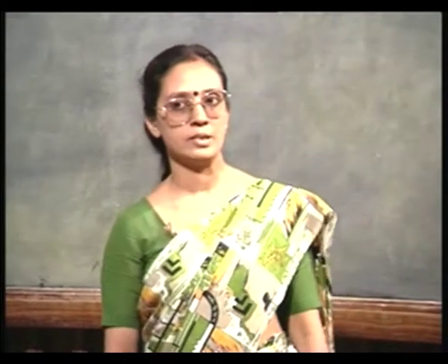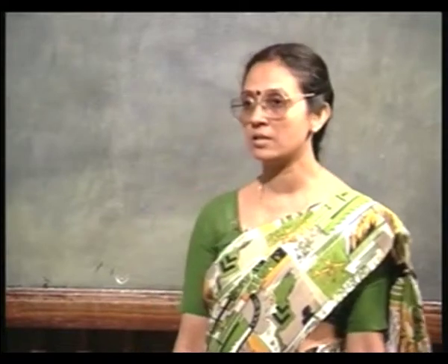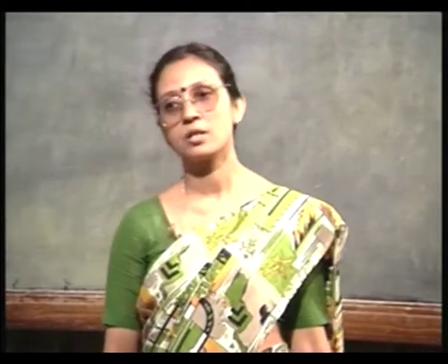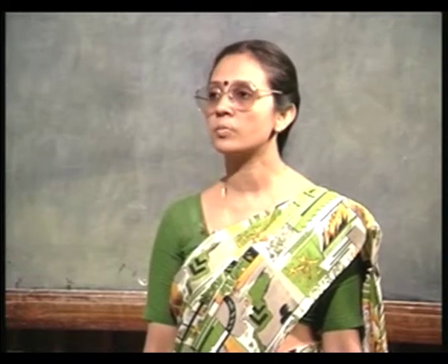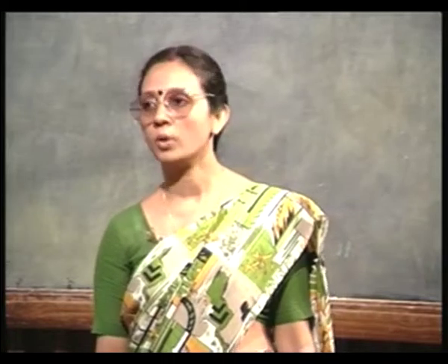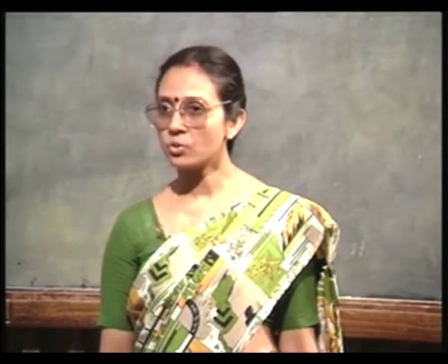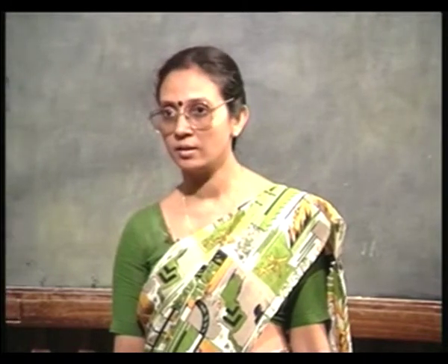What is the advantage? The advantage is that here I do not need, repeat, I do not need a crucible. In the Czochralski system, we needed a crucible to hold the charge. The crucible was made of quartz, silica. So, that was the primary source of oxygen in silicon.